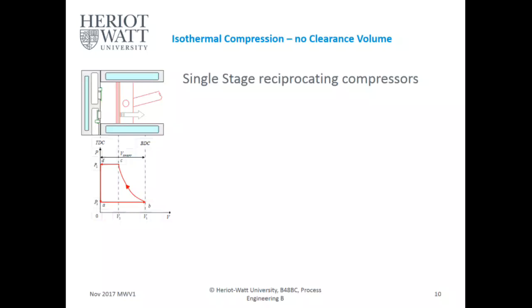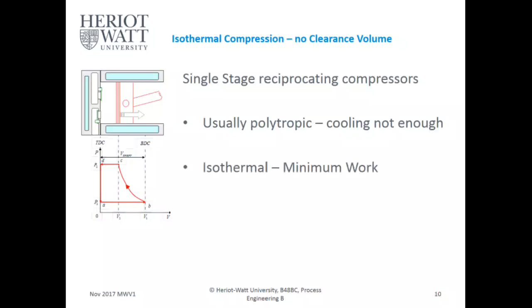So let's talk about single stage reciprocating compressors. Fun stuff. These are usually polytropic, so cooling is not enough, because they're cooled by air or water at any stage, so you cannot constantly cool it to compensate for the temperature change. It's always going to be polytropic, but the majority of the time you don't consider it to be polytropic in this course. Just so you know, they're mostly polytropic, and you will see that in fourth year energy generation and utilization. You will definitely use this, and it'll come in useful. Anyway, that's 2 years from now.